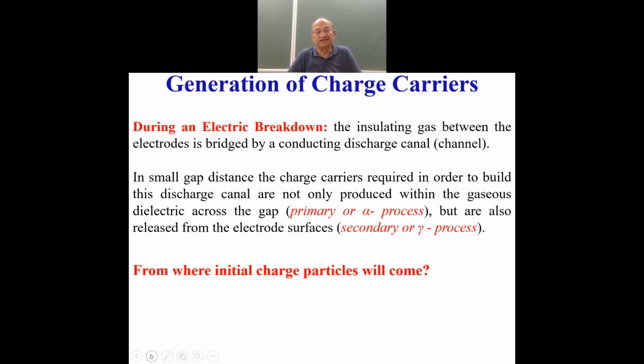What is an electrical breakdown? What actually happens in electrical breakdown? We know that when an insulating material loses its insulating property, a breakdown in the dielectric occurs. The breakdown in a dielectric is accomplished when you increase the applied voltage. The conducting path through the dielectric is formed, and we call it a canal or a channel. The two electrodes are bridged by this conducting path.